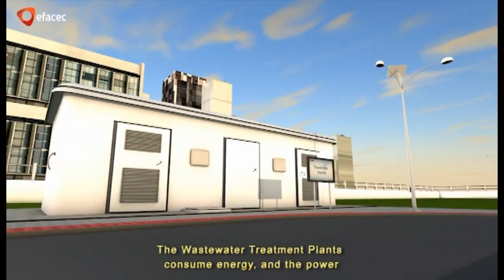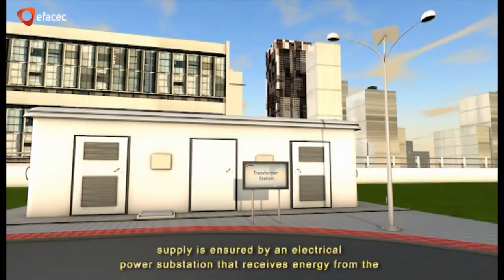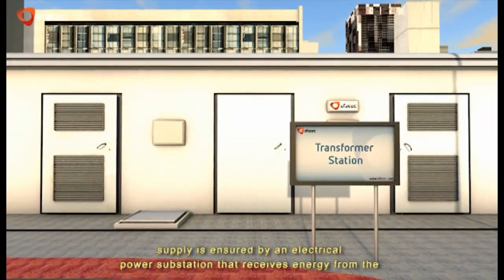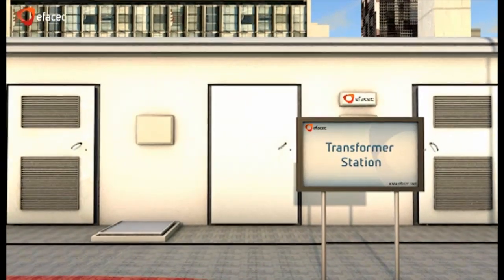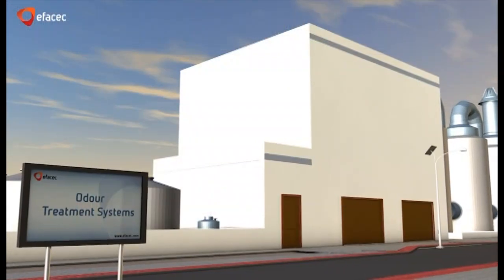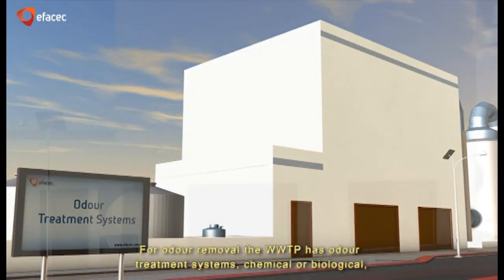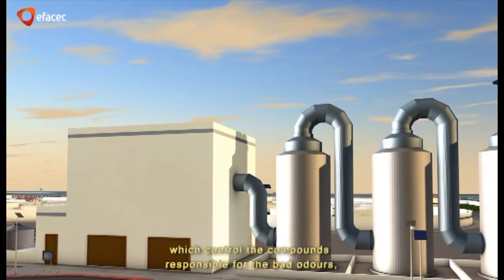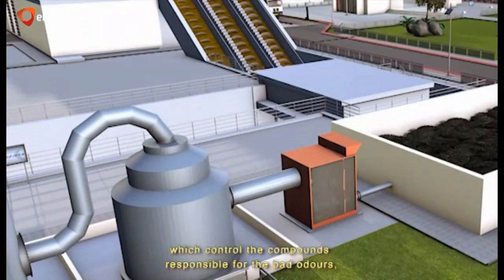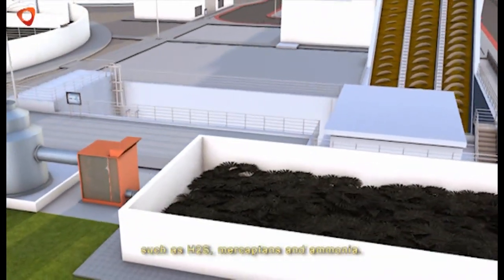The wastewater treatment plants consume energy, and the power supply is ensured by an electrical power substation that receives energy from the public medium voltage network. For odor removal, the WWTP has odor treatment systems, chemical or biological, which control the compounds responsible for the bad odors, such as H2S, mercaptans and ammonia.